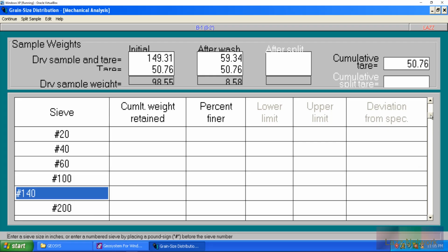So technically, kind of like what I was talking about, you have a separation sieve. So for this sample I do have material retained on a number 10 and greater. And your separation sieve is technically an auxiliary sieve analysis that you're going to do. So this is actually going to be a very interesting part, because this is set up much more differently than I have expected to see.